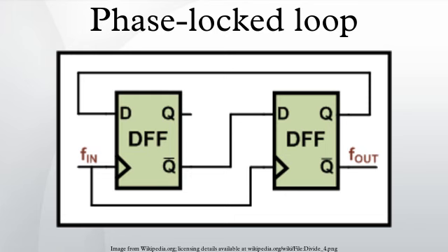Phase noise is another type of jitter observed in PLLs, and is caused by the oscillator itself and by elements used in the oscillator's frequency control circuit. Some technologies are known to perform better than others in this regard. The best digital PLLs are constructed with emitter-coupled logic elements, at the expense of high power consumption. To keep phase noise low in PLL circuits, it is best to avoid saturating logic families such as transistor logic